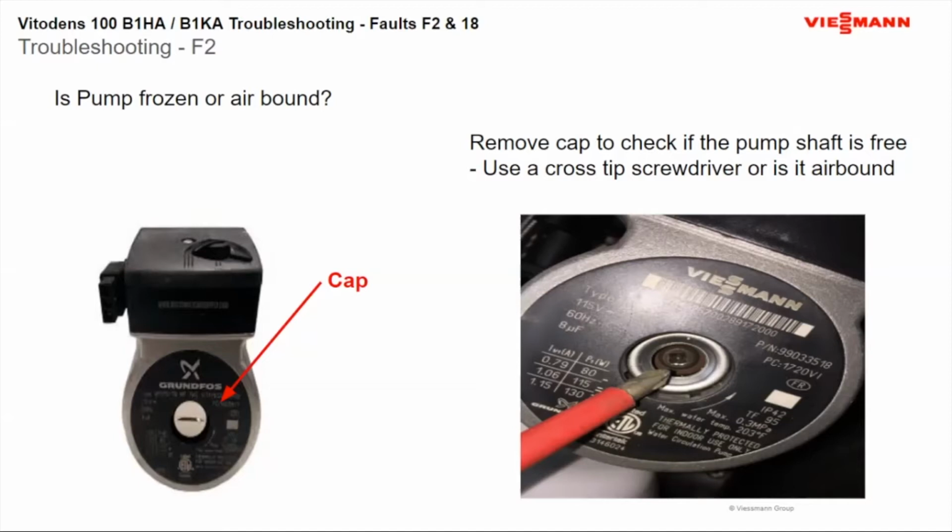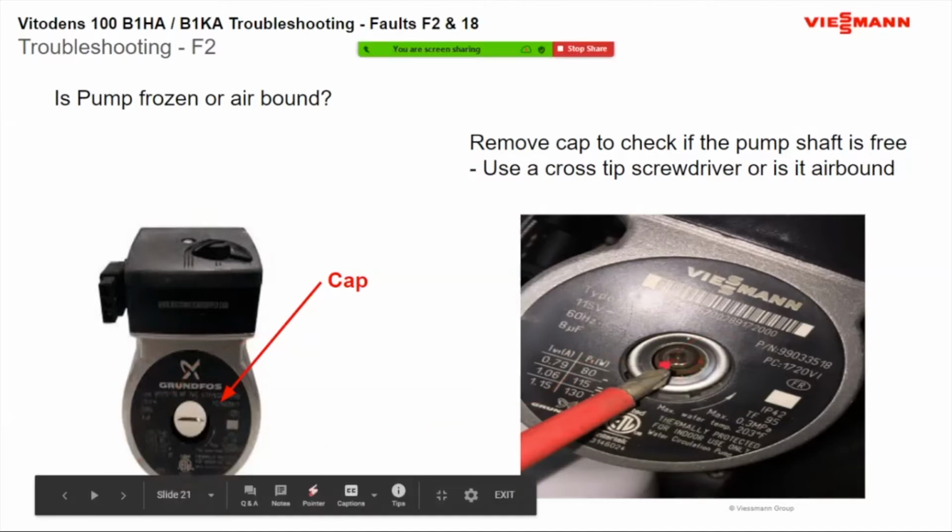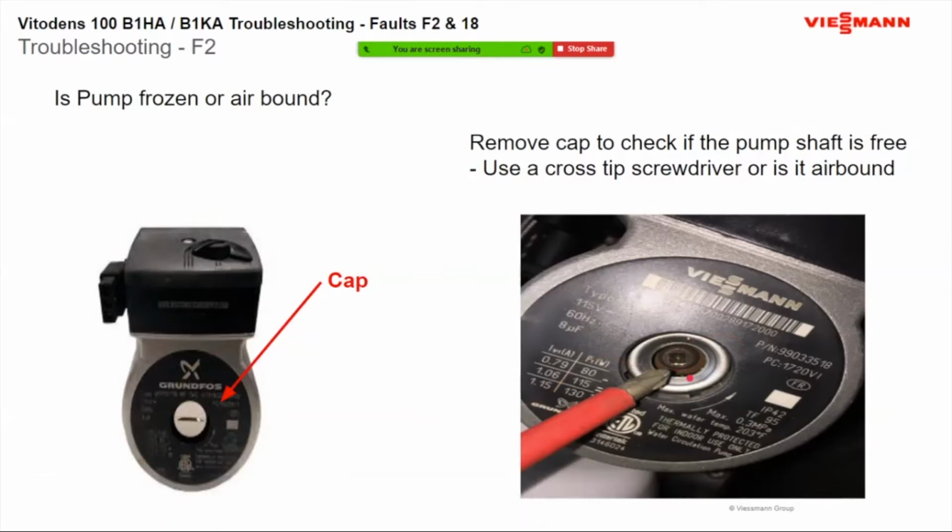The other thing is, if you look right in the center of that, it's like a cross tip slot. Some of them are torque heads, some of them are a flat tip. But that's just to check to see if your shaft is frozen inside there. If these Grundfos pumps sit around for a while, they tend to stick a little bit, and sometimes you just have to move the shaft back and forth, and that will free up the pump. But to do so, make sure you turn off the power when you're checking these things here.